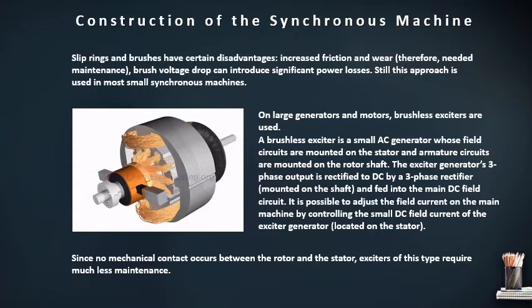Since no mechanical contact occurs between the rotor and stator, exciters of this type require much less maintenance. Brushless excitation is suitable for large generators, because if we use brushless excitation, we reduce the sparking as well as the power losses in a synchronous machine.